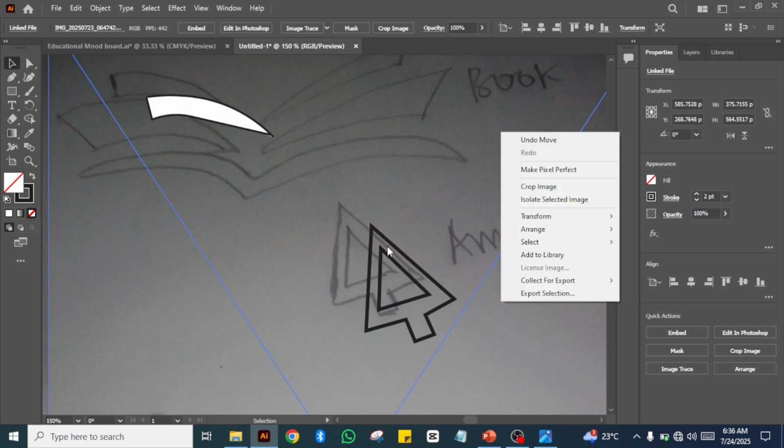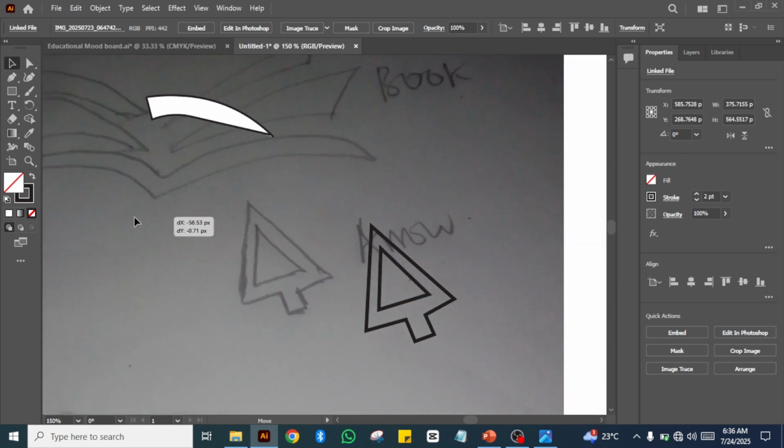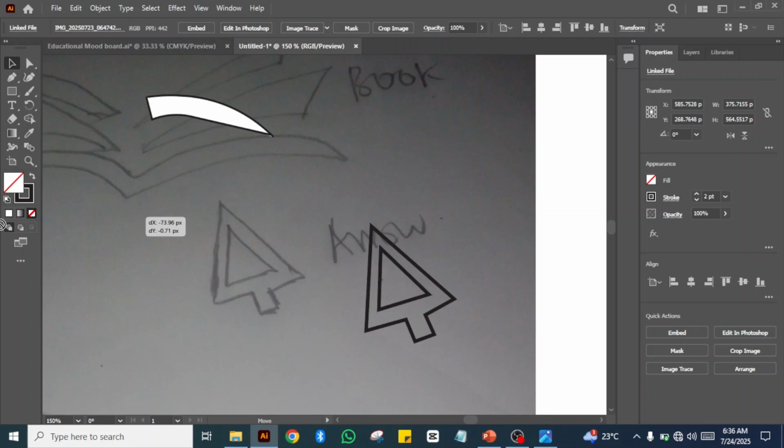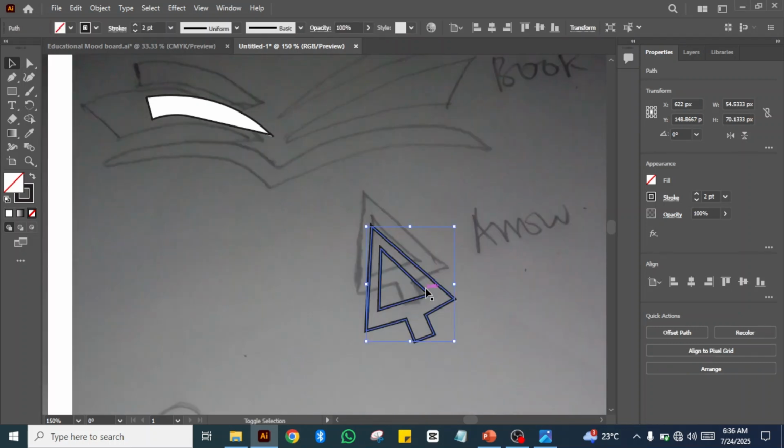No issue, no wahala, I don't have any problem since I have drawn it. Or you can just click on the shape, for example this one, hold Shift, and click on the other one. You hover around till you see something like a blue, and you click on it. Make sure you select both shapes in order to group. Click on the shape on the inside, click on the shape on the outside, right click with your mouse, and Group. Are we together till there?